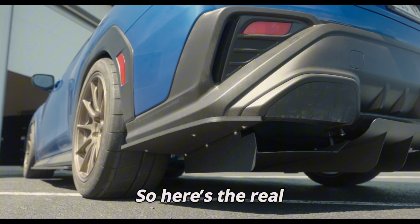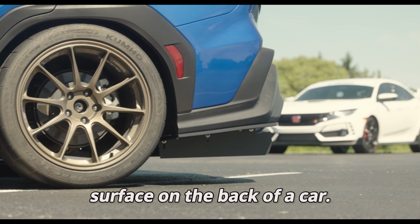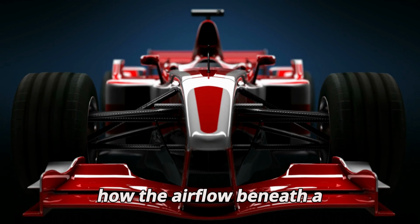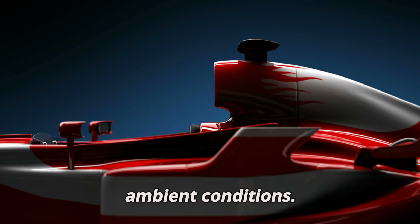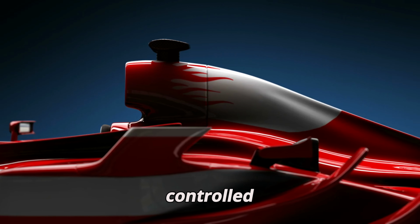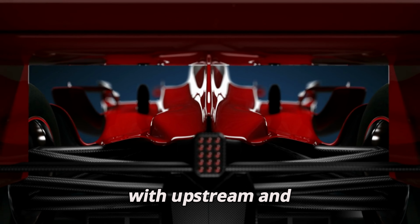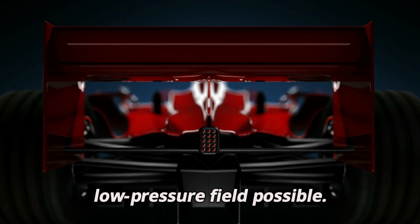So here's the real takeaway. A diffuser isn't just a shaped surface on the back of a car. It's a pressure management system, one that controls how the airflow beneath a car transitions back to ambient conditions. It uses expansion, controlled deceleration, and careful interaction with upstream and downstream flows to maintain the deepest low-pressure field possible.